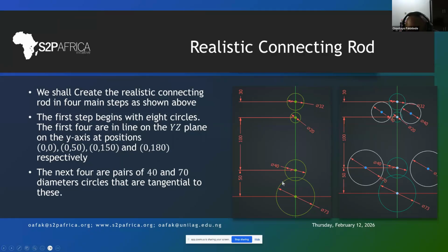Then I go on top of the line, and I make sure I retain the line. If you are still on the line, you will see a curve tool. If you don't see that curve tool, don't press. If you press when the curve tool is showing without moving it, the point will be on the line, and you can do your circle of diameter 40 here, and make sure that the distance between the two centers is 50. Once you've given the diameter of the circle and the distance of the centers, this also will turn green.